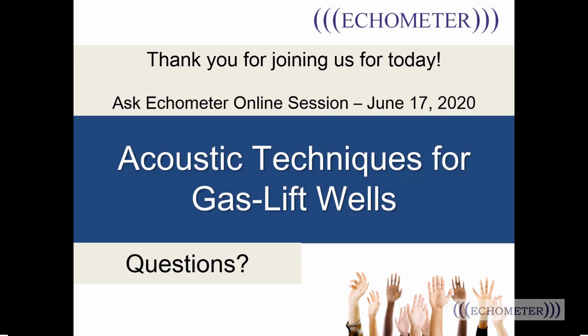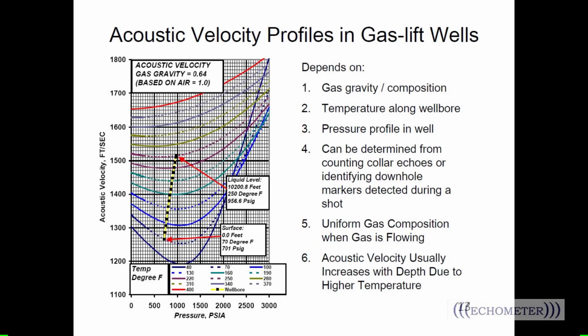You want me to try to answer that, Carrie Ann? Sure. Hi, Bill. Hey, guys. There's two temperature profiles. There's a temperature profile in the casing, which we typically see, and then there's a producing temperature profile in the tubing, where the producing fluids control the temperature in the tubing. So a fluid level shot down the casing is typically going to be based on the geothermal temperature gradient of the earth, and that pretty much controls the temperature profile, the earth temperature in the casing. It may be a little bit higher if you're producing liquids.